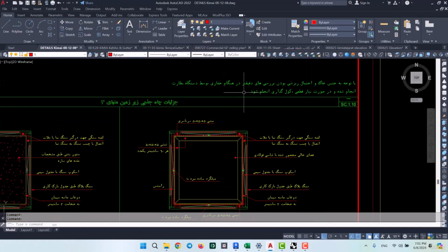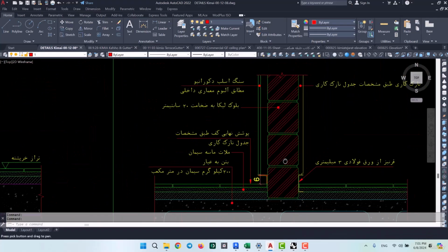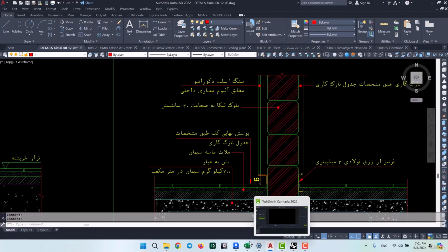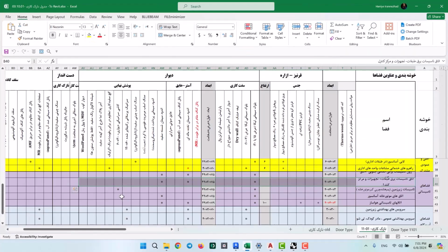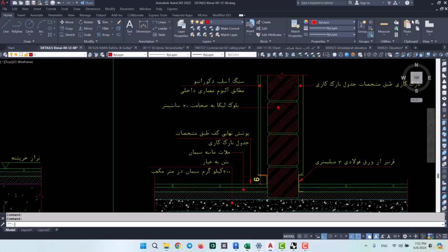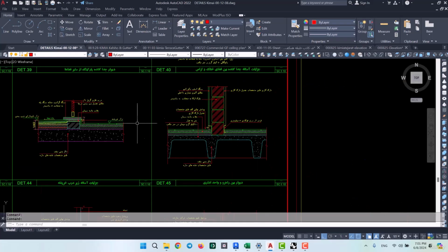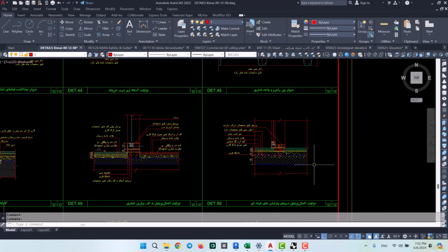So I'm going to go over here and see if I can find it in the details. Usually they tell it to you directly. Also, you could check around the finish table and see if there is anything about the thickness of those walls or not. For example, in this table we have here, it says nothing about that. Now, if we take a look in CAD, we can see this wall right here along with its finish wall, by which we could figure out the thickness.